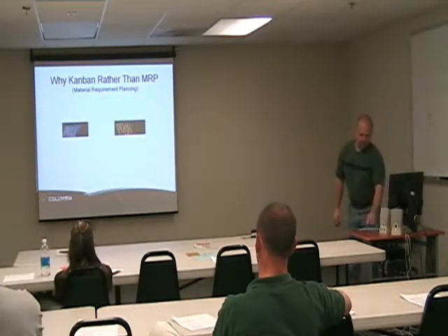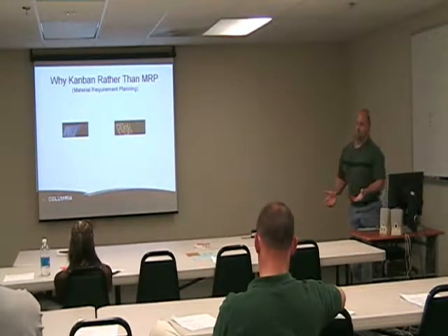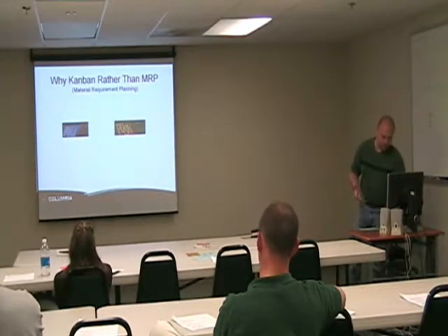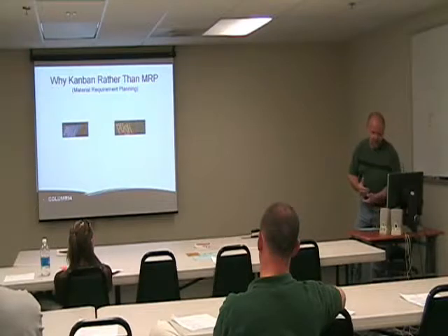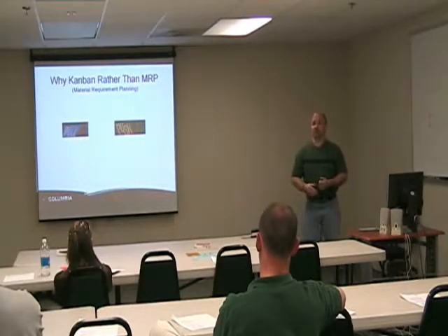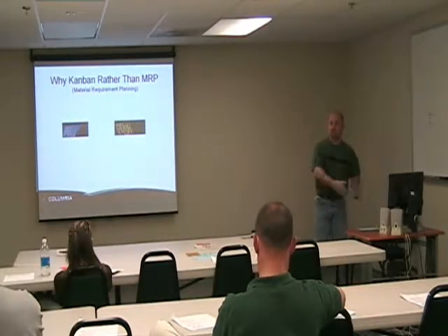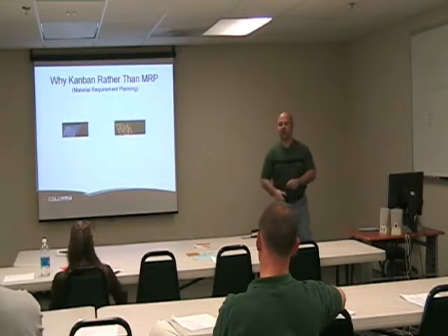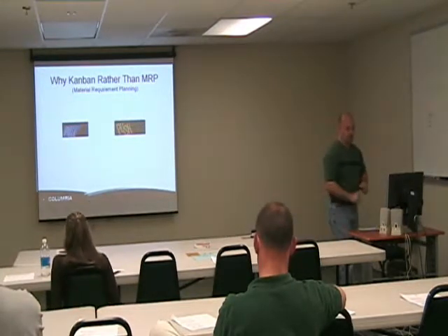Now, why do we want to use Kanban rather than our MRP system? It's a system that works for a lot of people, and it is a proven way to do things, but Kanban is a pull system. And in pull production, it gives a signal or authority to produce a part based on the demand of that material from your customer. So they are pulling from you what they need. You don't want people pushing parts on them, and we'll go into that here in a little bit too.